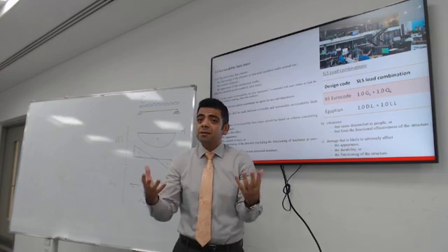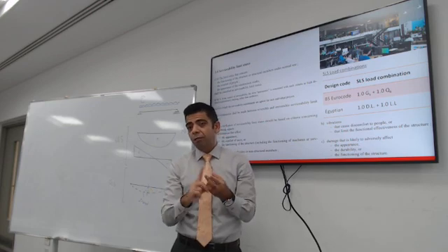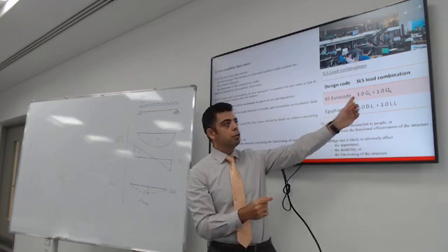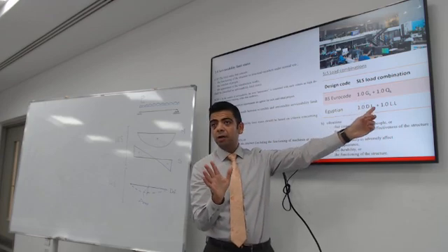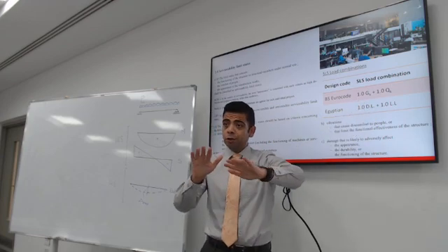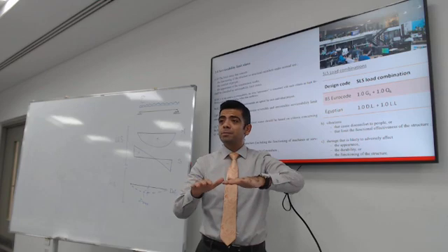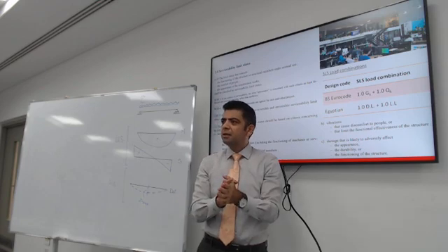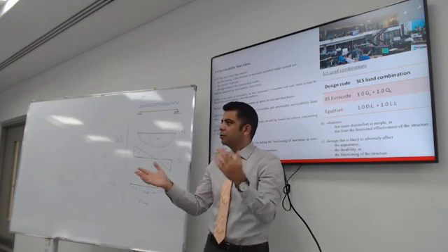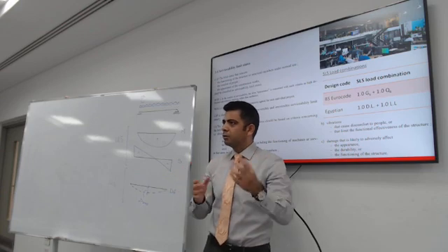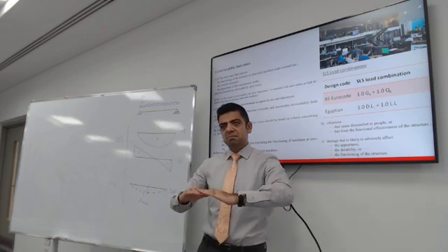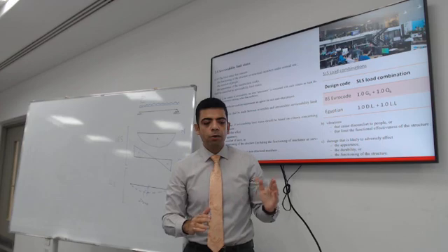So if it's serviceability, deflection, deformation, or vibration, use the actual dead and actual live. Just use the actual conditions the structure will be exposed to. Does that make any sense? Do you understand the difference between service load and ultimate load? Ultimate is factored. Service is the actual thing. So the question comes,